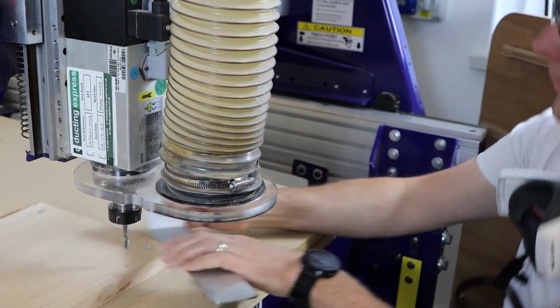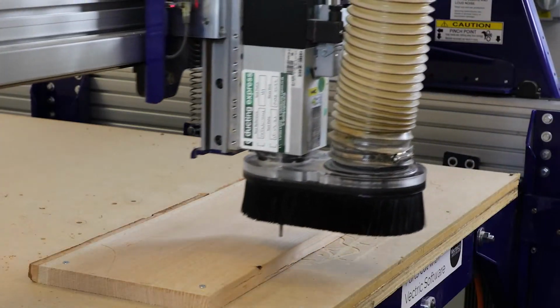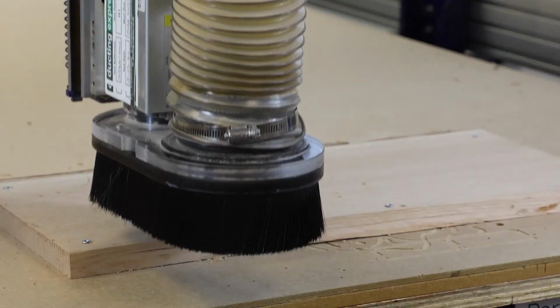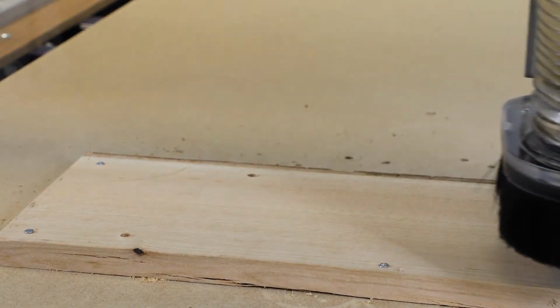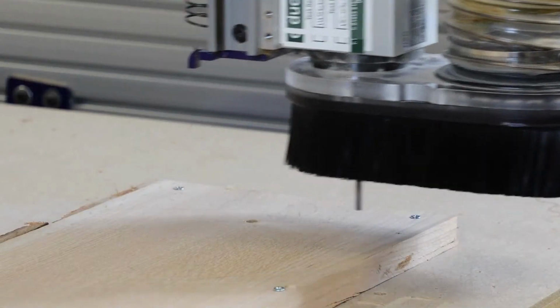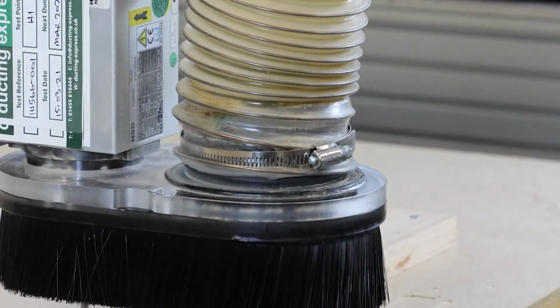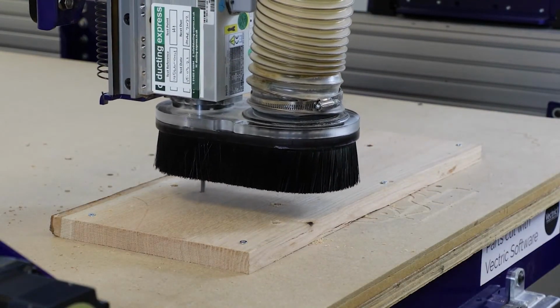We're going to start off with our end mill, and we're going to go in and cut the dowel holes, and then we're going to cut the holes for the pin to hold the top of the bottle together. These are just simple pocket cuts at specific depths.